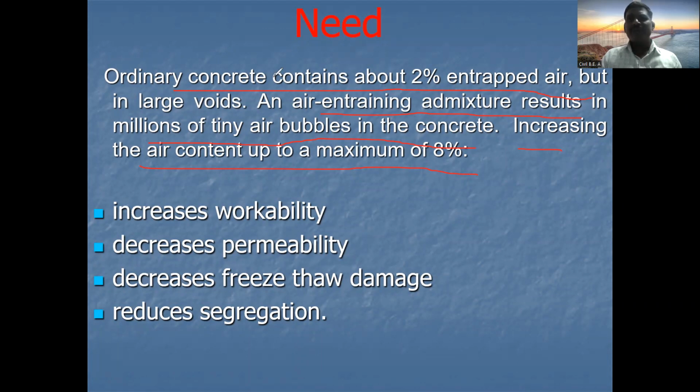So why do we have to increase that air? It increases the workability. If we increase the content of air, up to a maximum of 8%, we can increase the workability of concrete. Then it decreases the permeability, decreases the freeze-thaw damage also, and reduces the segregation.